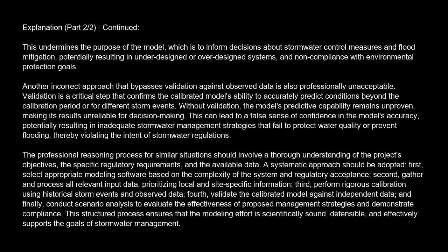Third, perform rigorous calibration using historical storm events and observed data. Fourth, validate the calibrated model against independent data. And finally, conduct scenario analysis to evaluate the effectiveness of proposed management strategies and demonstrate compliance. This structured process ensures that the modeling effort is scientifically sound, defensible, and effectively supports the goals of stormwater management.